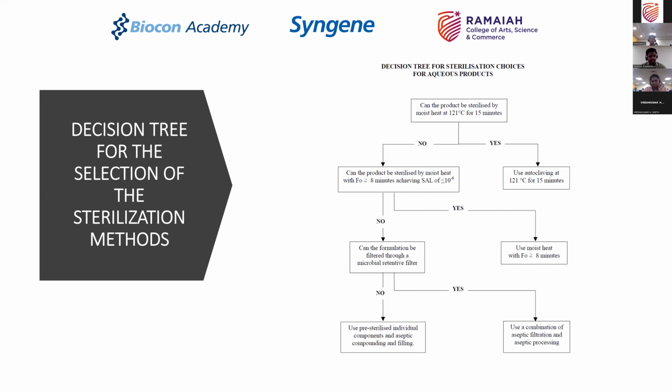As I said, the condition at which you are doing terminal sterilization is what you are playing around with. These values are given by CPMP. As I said, 121 for 15 minutes is something given in the guideline. But on what condition? At saturated steam at 121 degrees centigrade at absolute pressure of 1.2 bar for 15 minutes, you will achieve sterilization.